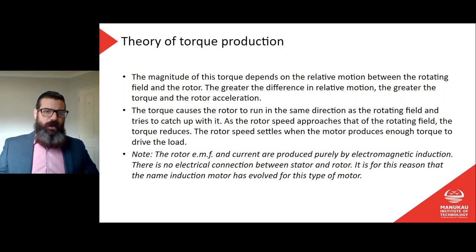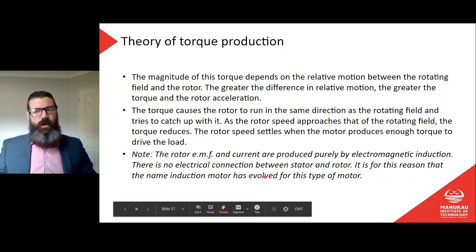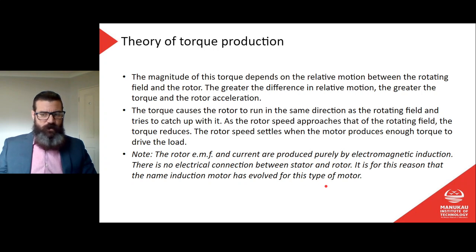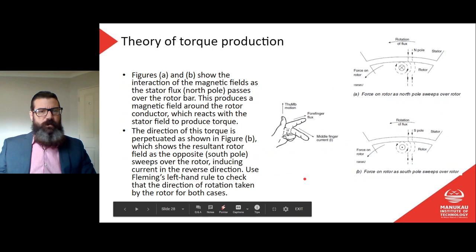Note, the rotor EMF and current are produced purely by electromagnetic induction. There is no electrical connection between stator and rotor. It is for that reason that the name induction motor has evolved for this type of motor.